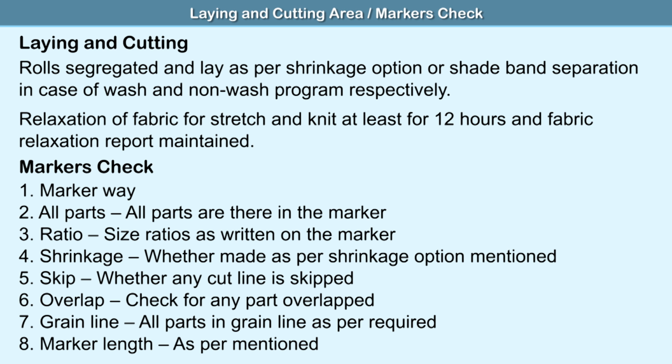Whether any cut line is skipped. Check for any part overlapped. All parts in grain line as per the requirement. Marker length as mentioned.